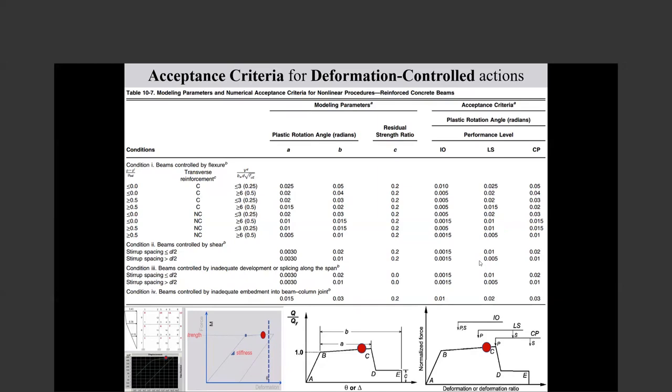It is very difficult to discuss, but in general, taller shear walls behave in flexure and undergo plastic deformation in the flexural hinges, and the shorter ones will go nonlinear in shear mode, because when they become shorter, they become very stiff in flexure, so the shear deformation increases. Therefore, the general characteristics are quite different.